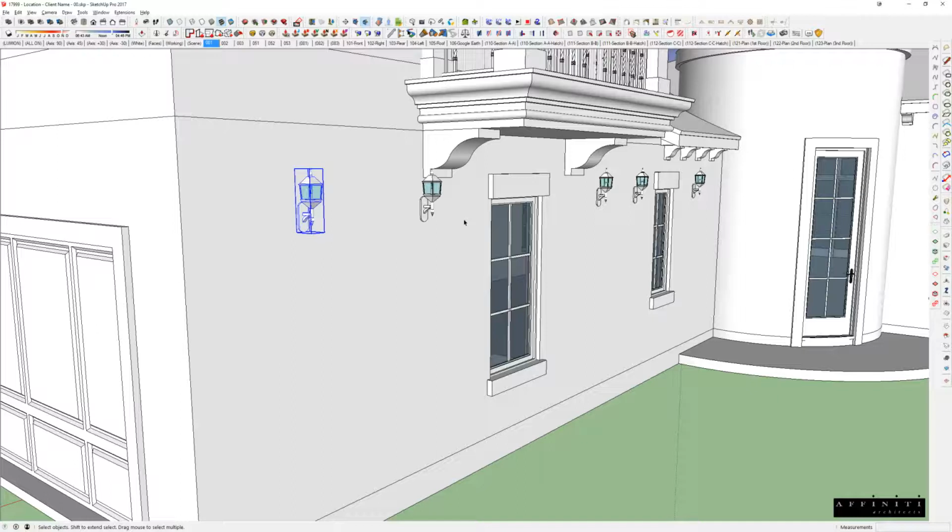So the biggest thing you need to be aware of if you do this component replacement is the origins. It always gets reloaded by its origin. This method actually gets very, very useful when you get into very detailed landscape plans. If you actually get a landscape drawing from a landscape architect, and if they happen to send you CAD files, which is fantastic, they have all of their blocks for their landscape.